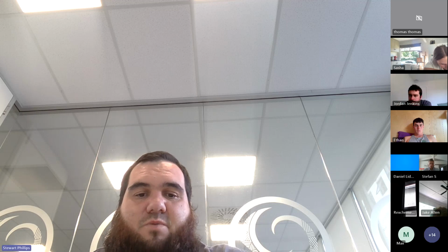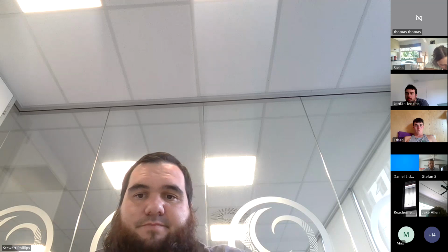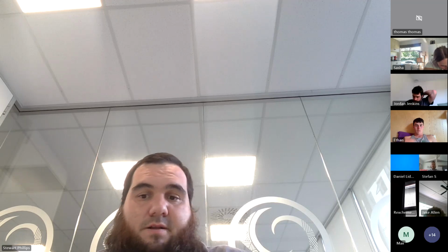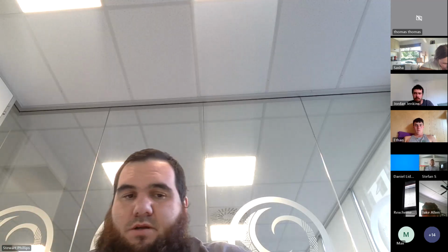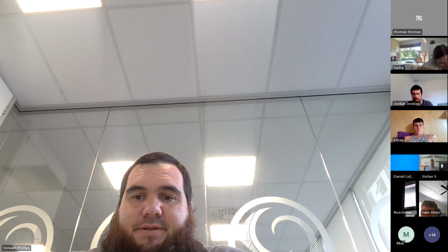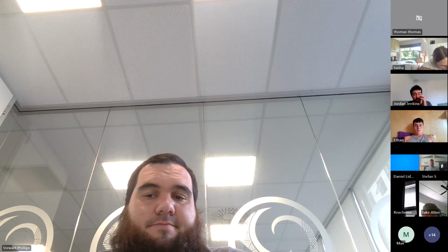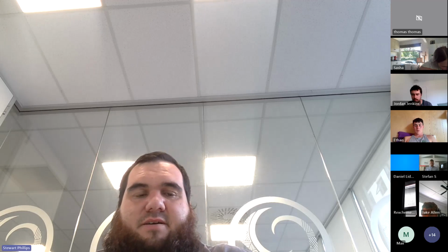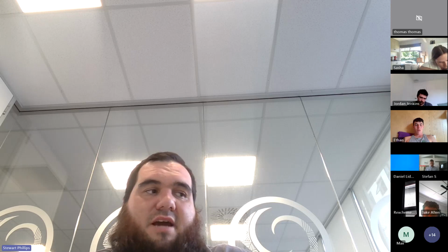Arc faults. So has anyone here installed arc fault breakers other than me? So they're not cheap, but they are quite an interesting piece of equipment because they detect the frequency at which the current's flowing.